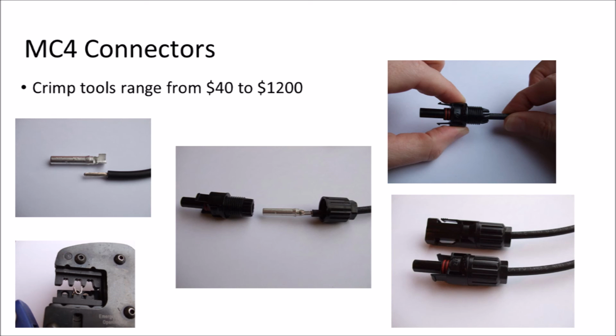One of the notable industry standards is the MC4 connector coming out the back of the solar panel. A common point of system failure is the field-made MC4 connector. Even when doing things correctly, it can be easy to confuse the male and female housings and metal connection tips of the two different connectors.